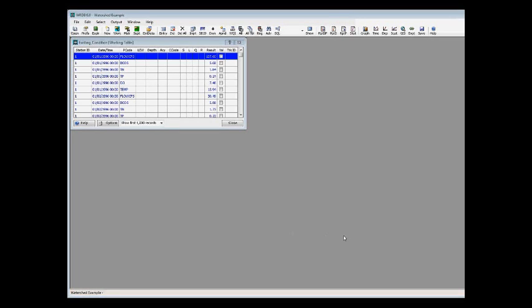Okay, we are now going to process the LSPC watershed time series results and pass them on to a water quality model. In this case here, we're going to use the example of using WASP, but there are many, many different ways to do that. As shown in the PowerPoint previous to this, we're only interested in sending one of the subbasins to the water quality model, and that's subbasin 1. So what we're going to do is execute a query to separate out just subbasin 1, and we are going to pass to WASP the flow, the BOD, the total nitrogen and total phosphorus, and the DO. And then we can actually pull the water temperature data in as a time function.